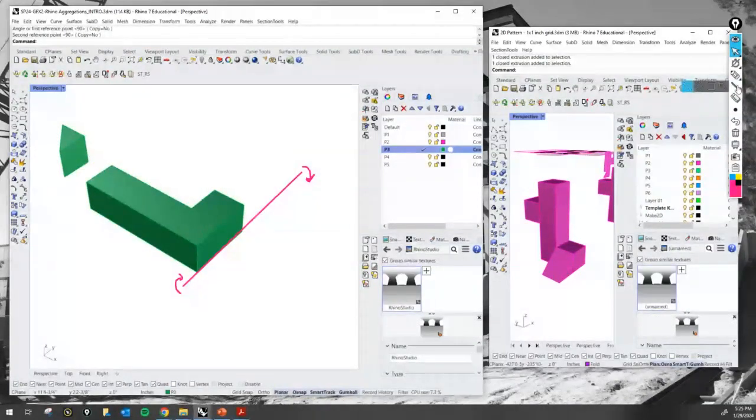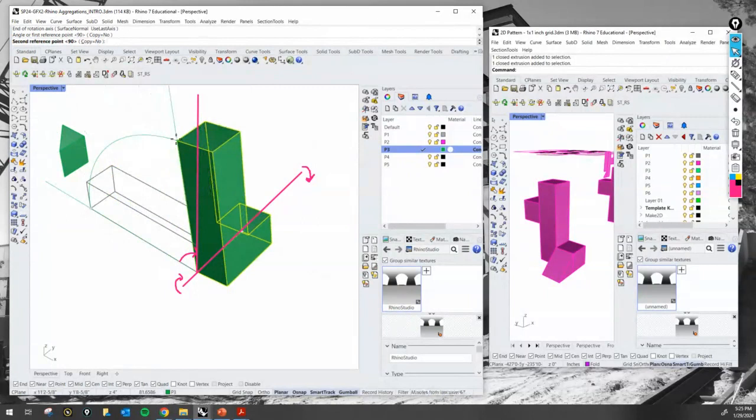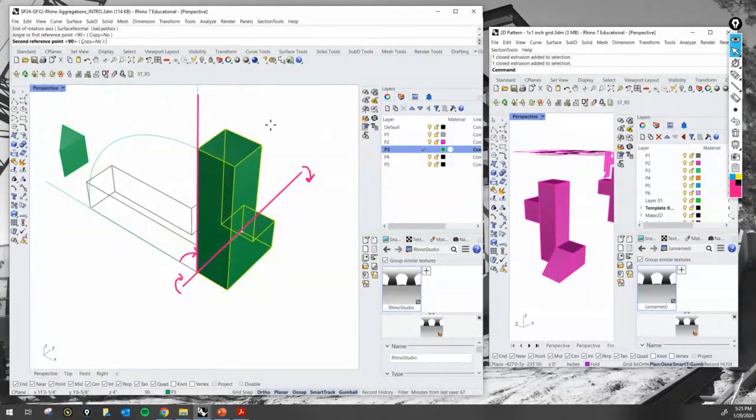So you can kind of draw that right here, right? So I actually want to rotate this 90 degrees like that. But I'm just doing that with the reference. So again, rotate 3D, right? Select this is my axis right here, and then this is my angle. I hold shift so that it snaps to that orthographic, and then that gives me my 90-degree angles. And again, that is now standing up.